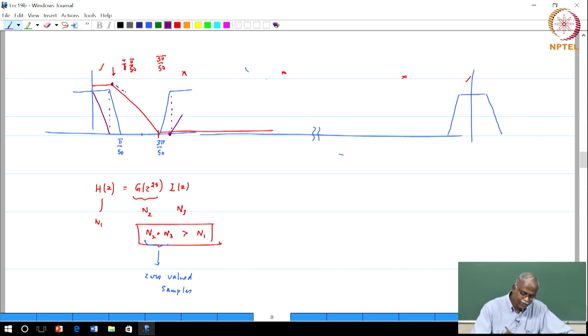So, you could have designed it slightly wider and therefore a lower order filter as well, because ultimately what you want to kill is the presence of the signal. The filters are not the ultimate thing you have to worry about, it is where the signal lies. So, as long as the filter has the response of that purple line, it will remove the unwanted images and you will get the desired frequency response.